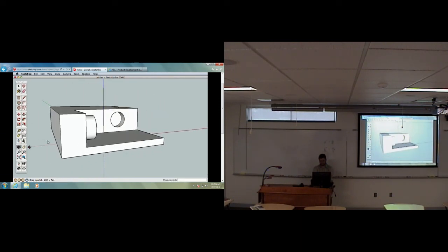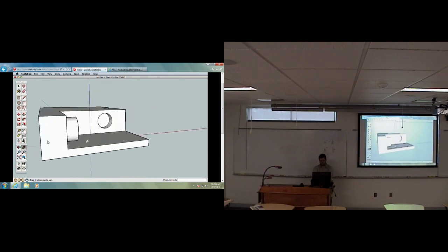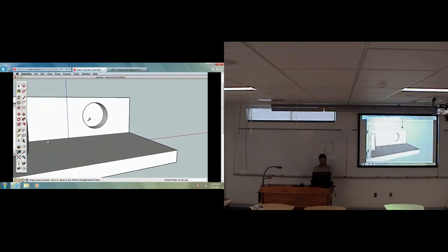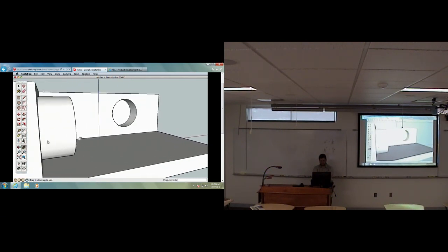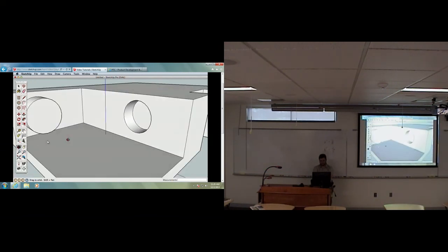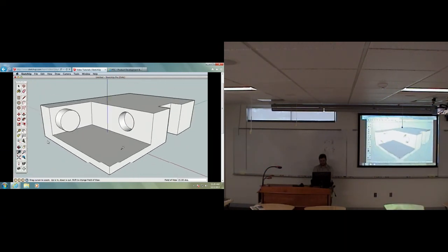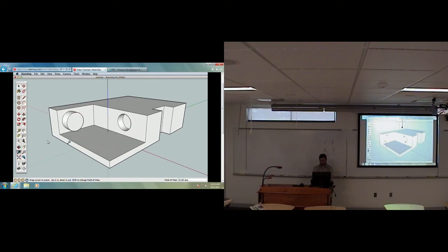Now try practicing using orbit, pan, and zoom together. Zoom in, orbit, pan, orbit, zoom, and so forth. Navigating is essential in SketchUp, but going back and forth to pick the icons seems slow and cumbersome, which is why we've built all the navigation tools into a 3-button scroll wheel mouse.